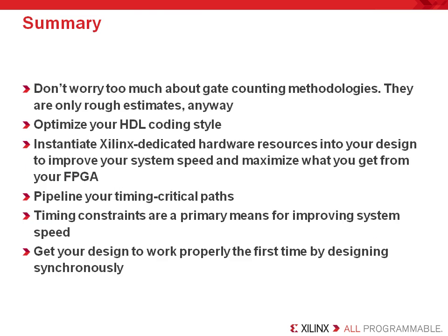In summary, don't worry too much about gate counting methodologies. Again, they're only a rough estimate. It is very important, of course, to optimize your HDL coding style, and of course, instantiating Xilinx dedicated hardware resources into your design improves your system speed and maximizes the amount of logic you can pack into the FPGA.